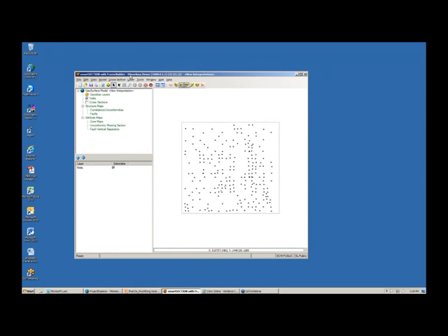smartSECTION's unique in that by default it wants to look at all the well data in a project, even if you do have a smaller AOI active. In this case, I do have a smaller area. Therefore, a project with hundreds of thousands of wells can act lethargic when it's first opening up. This is because the software is trying to access hundreds of tops in hundreds or thousands of wells and make mathematical calculations on all these tops so that it can generate surfaces.